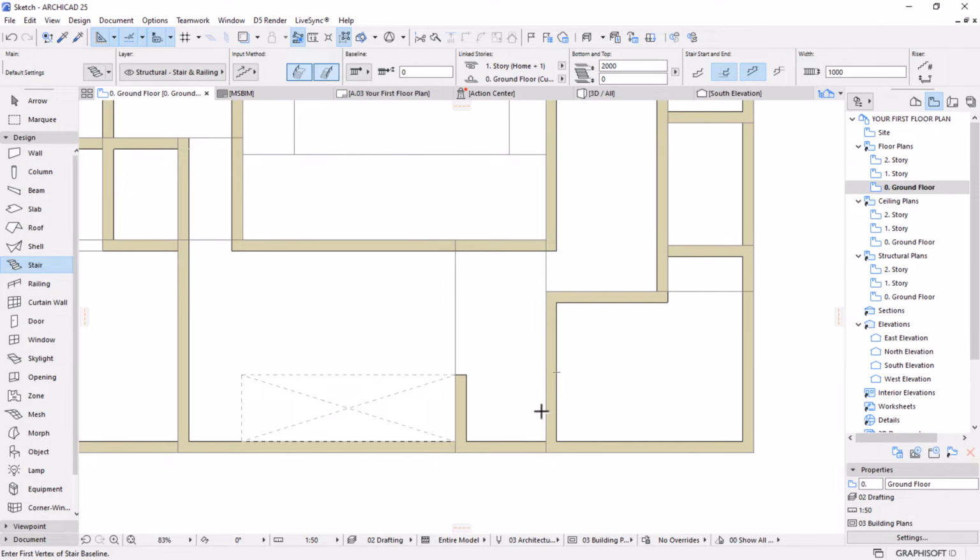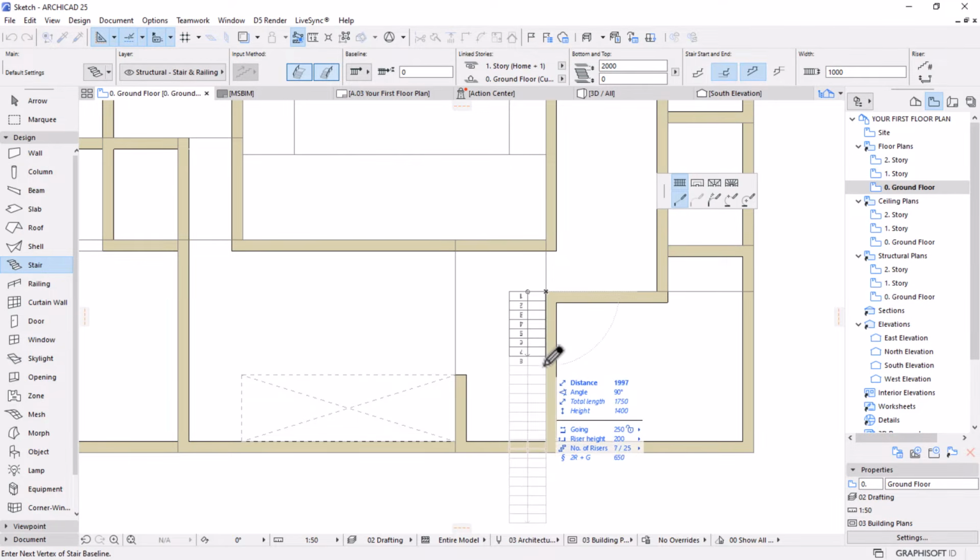And then I'll start my staircase from here. It's going to be a dog-legged staircase. I'll draw it like that, then come somewhere here. I'll count the number of stairs for the first flight. For the first flight, by standards at least 10 steps will be sufficient, or comfortable enough for someone to use this staircase. So let's just end by the 10th step and then click.